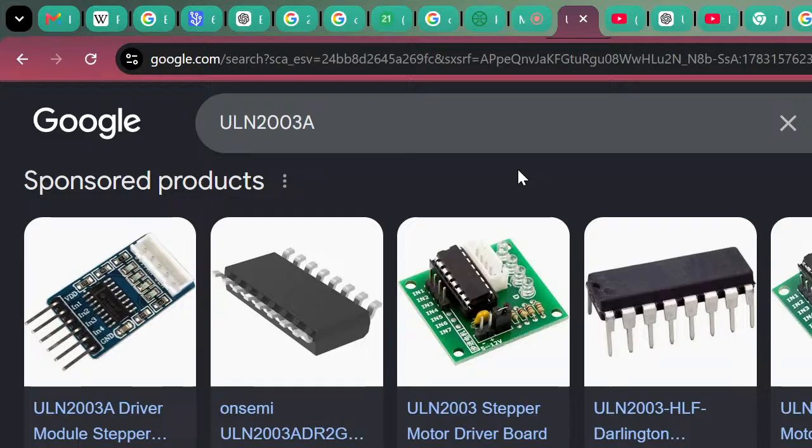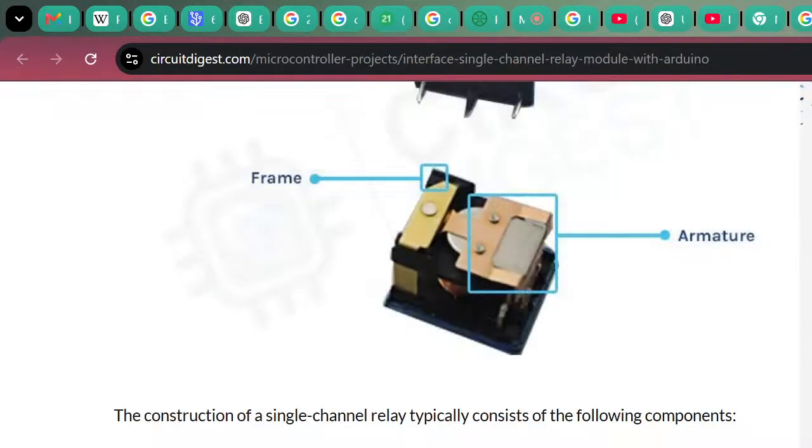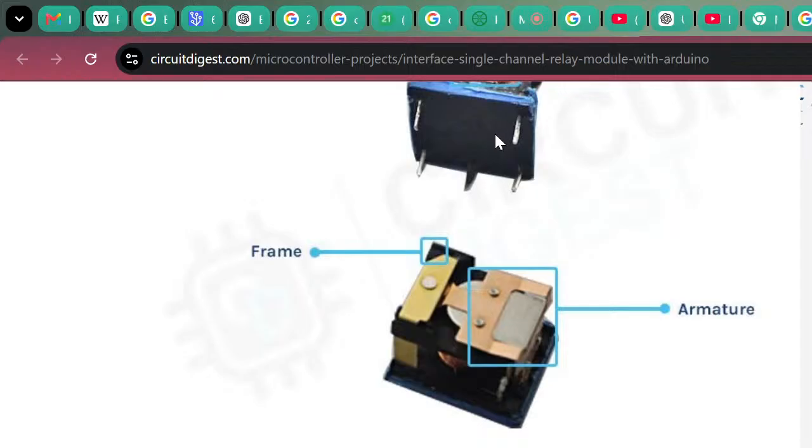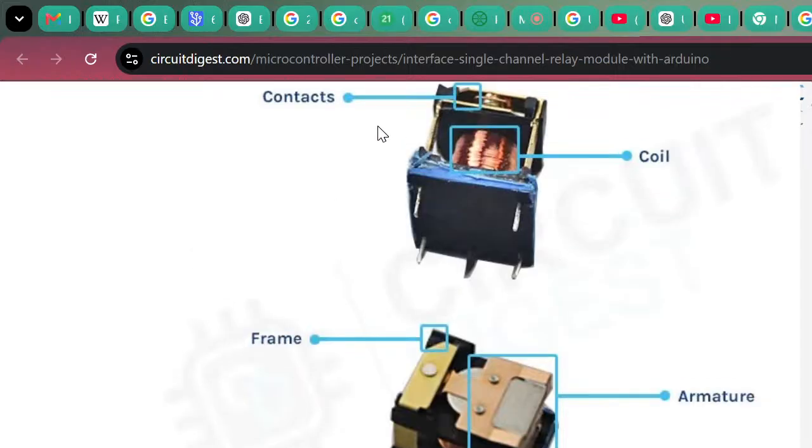But if you are trying to operate a higher voltage application by connecting it with something like an Arduino module or ESP32, those modules also run at lower voltages, but still it is not a safe practice to directly connect these two coil pins to the Arduino or ESP or any other microcontroller operating at lower voltages.